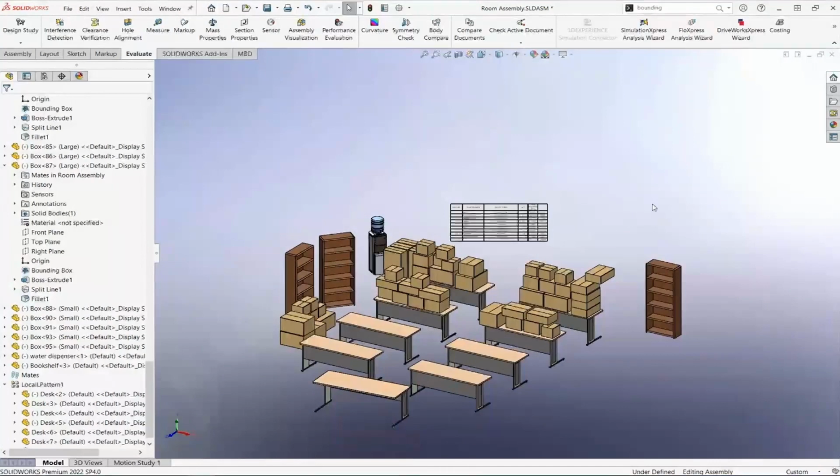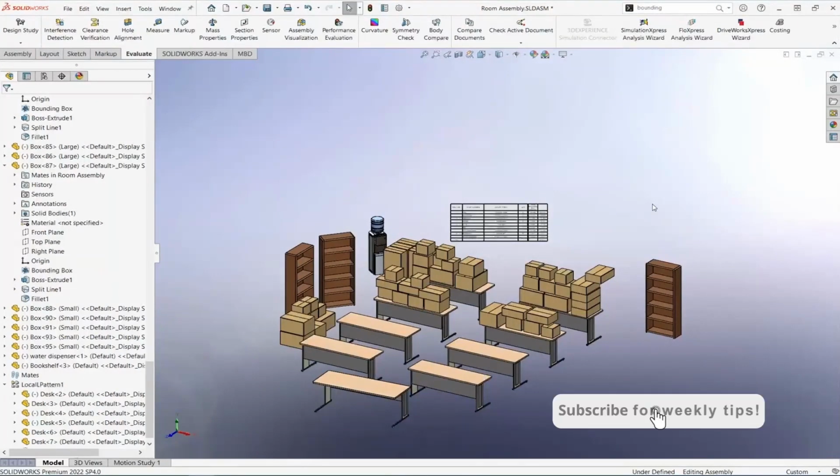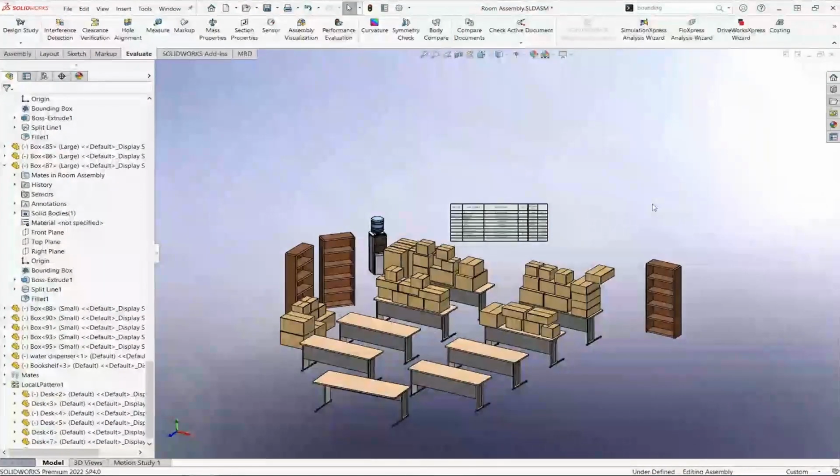And I know that a 20-foot van has about 1,000 cubic feet, and a 26-foot van has about 1,600 cubic feet of space. And now, by using SOLIDWORKS, these advanced selection techniques, interrogating mass properties, and using bounding boxes, I now know that I have to order a 26-foot van to move all of the stuff in 3 rooms like this.